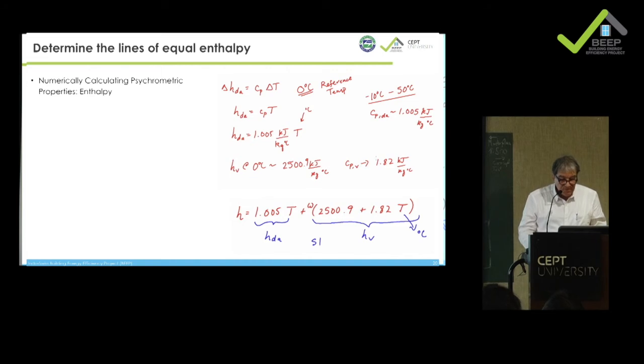So now if we look at what is the enthalpy of dry air, generally, from the ideal gas law, you can say it is proportional to the capacity, Cp, the capacity of the air, multiplied by the temperature. And as a convention in the psychrometric diagram, 0 degrees is 0. That means Cp into T at 0 is 0. That means the energy of the air at 0 degrees is considered as 0. If it's below 0, it will be minus. If it's above 0, it will be plus.